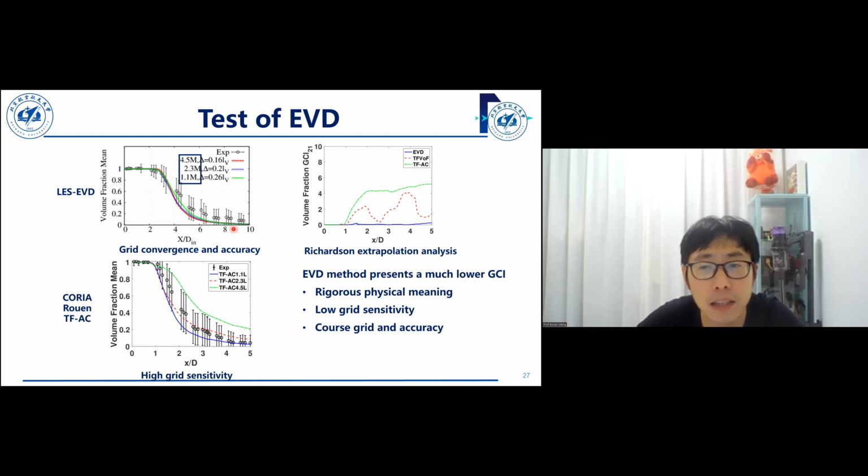The second test is Rayleigh-Plateau instability. Here we see spray breakup and atomization in a stationary air environment. We see dripping, Rayleigh, wind-induced, and wind atomization here. For our Rayleigh-Plateau instability, we test our case in the extreme low Weber number and velocity regime. Here the jet diameter is about 2.51 millimeters from a test in 2009.